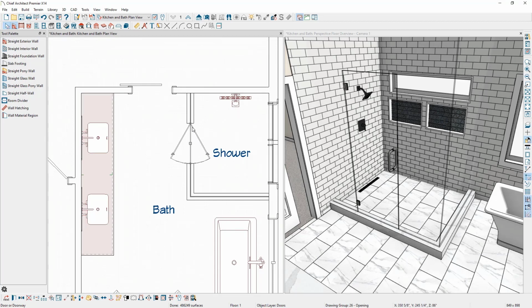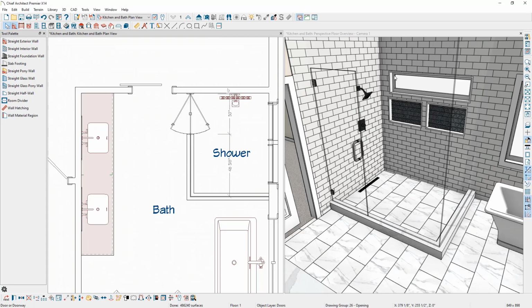And then next, let's get this door positioned next to the drywall so that it's residing on the tile backsplash layer. So what we're going to do is we're going to turn back on our temporary dimensions. In the floor plan view, click on the door, and you can see where that dimension is coming in. And we're going to click on it, specify that it's going to be located a 1/2 inch away, which is the tile thickness, and then press enter. And you can see how that door looks in the plan.